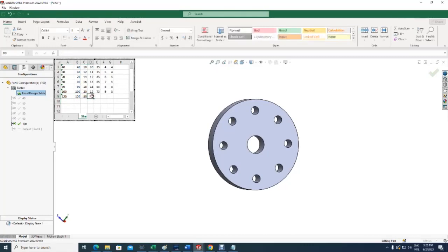You want to be careful here. Let's put here, I would say 18. I mean, I'm making this part on the fly, no thought about it. This goes by 5, so 85 will do. What is this? That's the hole diameter, so that's 9. Let's make this 10. And the number of holes, 10. Let's see. That will be interesting.